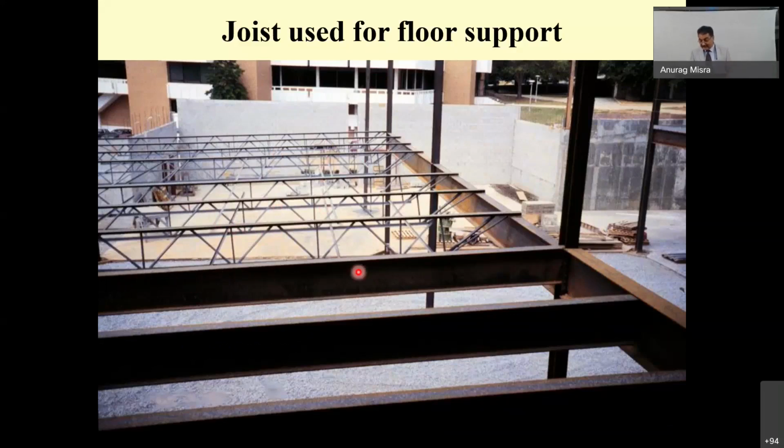So you can see there are some steel beams which are connected to the cross beams, and then depending on the requirement, you could create some open web sections, they are called, some truss kind of structures which are attached to the beam, and then you could put the deck sheeting and complete the casting of the slab, and put it to use for service.